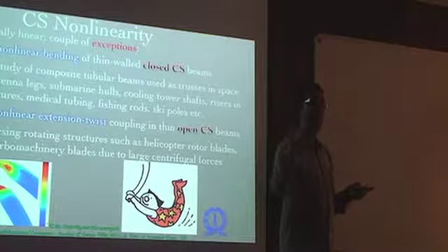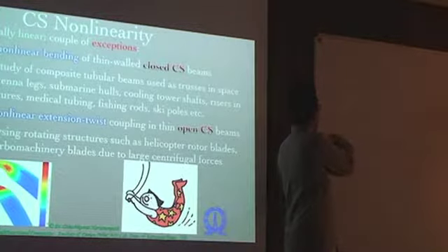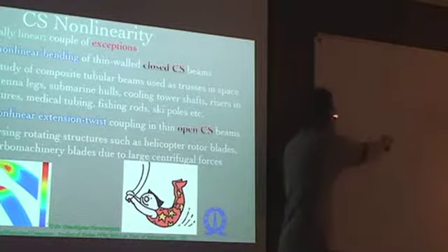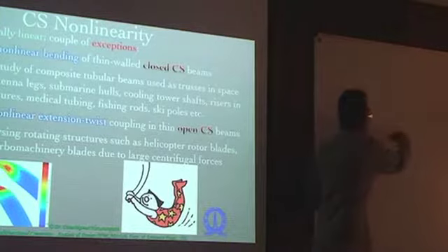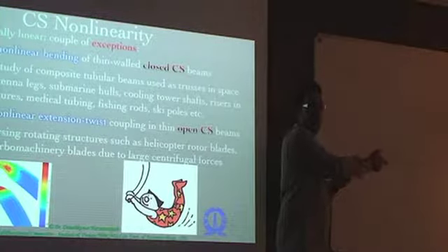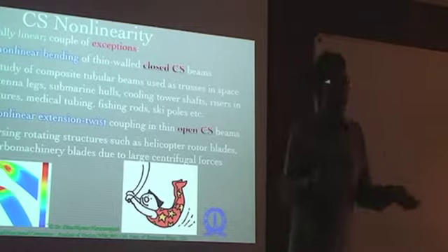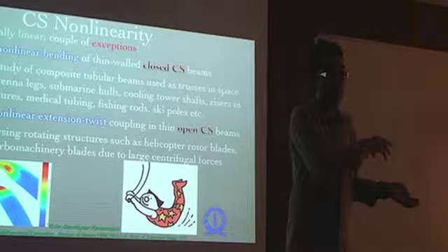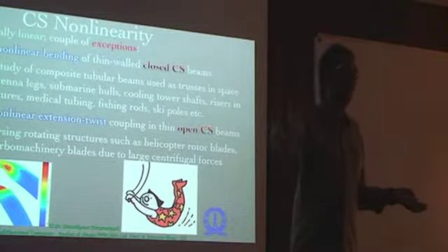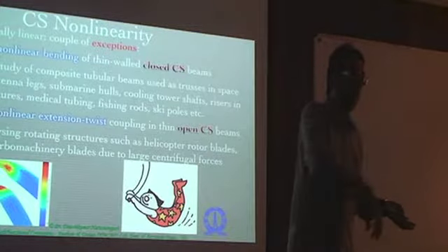Now that M2 kind of a bending is basically going to be related to this kappa 2, and if this is a nonlinear thing, then your S33 can depend on kappa 2. So there is an indirect way in which it is contained in the cross-section analysis, but not explicitly. You're not taking the loads into picture there.